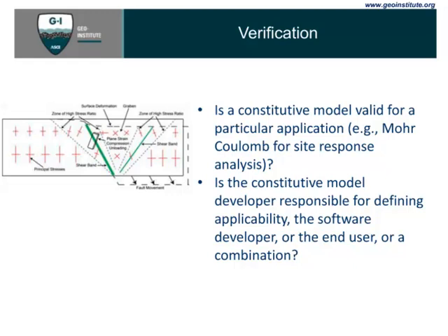And just ignore the titles on these slides. I flipped them for the next two slides. But this is validation. And a really important part of numerical modeling is making sure that we validate a particular model that we have against reality. So would you want to use Mohr-Coulomb for site response analysis if you expect a really nonlinear response? Probably not. These guidelines would not address specific technical issues like that, but rather who should be responsible for validating models.